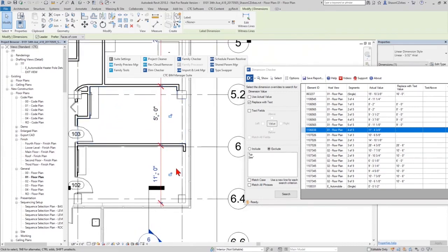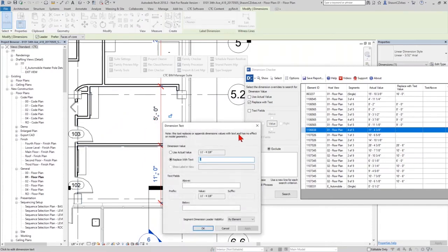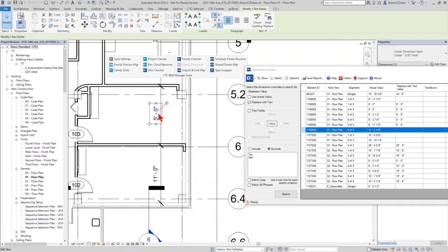Now, you might not be able to correlate in your mind feet and inches to the metric equivalent, but you can probably tell here that 11 feet at this dimension and 5 feet at that same visual dimension, something's obviously not right here. What somebody did at one point was they overrode the dimension with a period, and they put their own text string on top of here, which is a piece of opaque text, right? Now, on a printed document set, no one would ever know this until you get to building it and someone's like, hey, what's going on here?